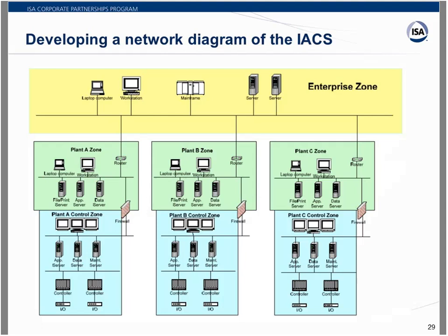The likely event is that in plant zone A, right here, a contractor was working in the area and brought down the data connection inadvertently, and that section of the plant went out. We can run the remainder of the plant for 20 hours before we have any problem with this. There's actually no impact for 20 hours or less. That's an important thing to know, right? Because that's going to affect how you design your cybersecurity solutions. A contractor dug up the fiber optic line, but we've got tank storage for 3 days. Nothing happens if we get it fixed in 3 days. That helps you focus on where it's important.